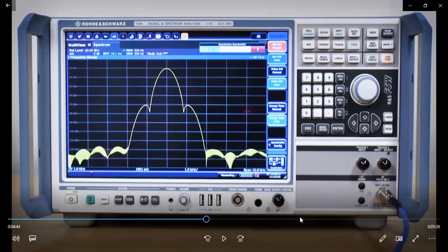and span. Okay, we already discussed what the span is. It is the whole range of the frequency that you have on the display. So as you reduce this span, of course you have a better resolution within your display, right? If you have a long span, then the whole variations will have to fit in your display.